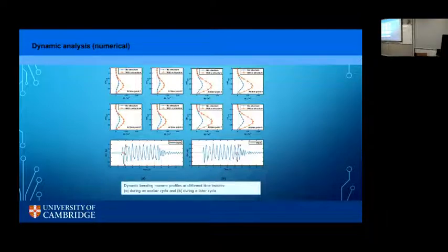If I take an early cycle like this, you can see at different points along the acceleration what the bending moments are, and you can see that they are increasing. If I take the same analysis, but look at a later cycle towards the end of the earthquake, you can see my bending moments have increased significantly compared to earlier in the same earthquake. Now, the magnitude of the shaking is almost the same for both, but because of the number of cycles, this thing got a lot worse. And this is something which designers must be careful about.